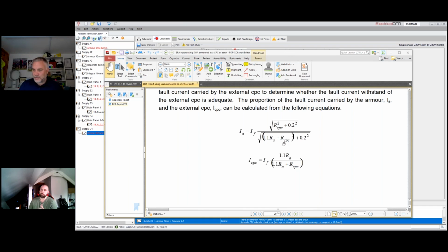With things like trunking, the value's 2.1. With conductors that go through conduit, I think it's 2.1 for those conductors too. I can't remember the number off the top of my head, but you see the thing. It's where we're looking at steel ferrous enclosures with steel ferrous elements in there. When we're using non-ferrous materials like aluminium, it's not a consideration, because the electromagnetic effects are minimal, not enough for us to be concerned about.